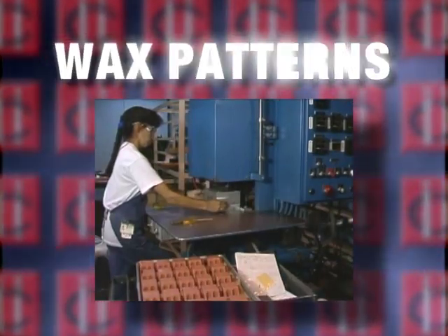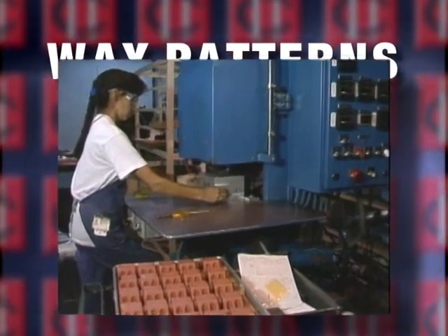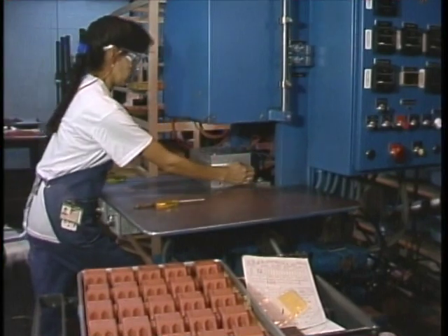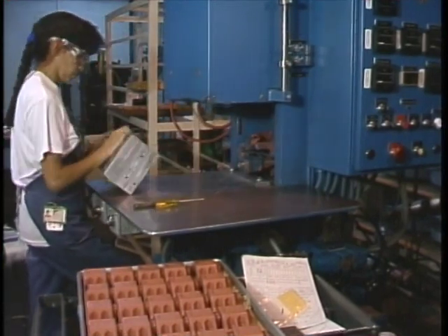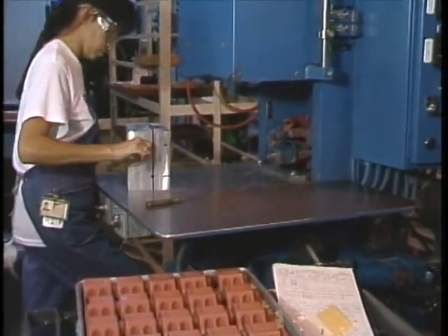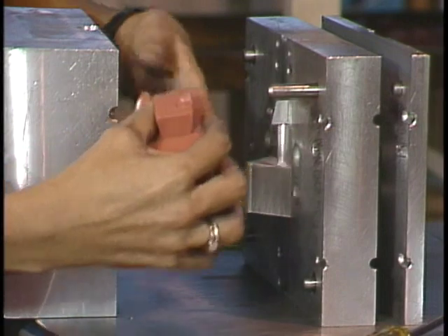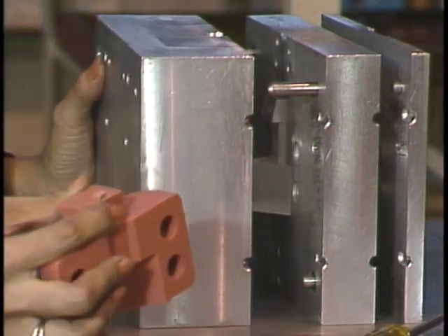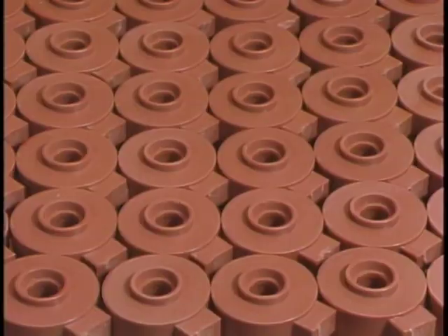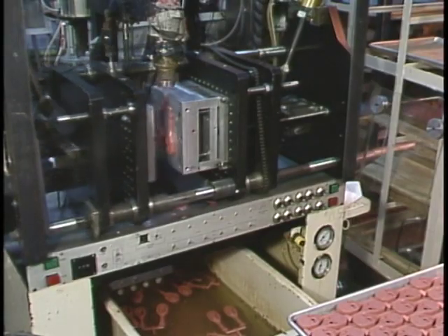Now, let's follow the investment casting process through some typical foundries. To begin the process, wax patterns are typically made by injecting molten wax into an aluminum die to make an exact replica of the part. Wax injection presses make larger, high-volume, and more complex parts feasible. Rapid prototyping speeds design and development and offers an attractive alternative for low-volume or pilot applications.